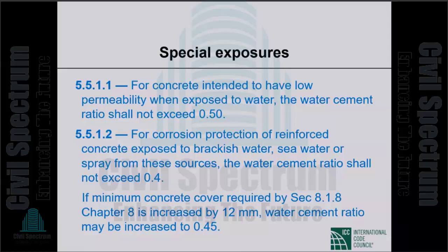Okay, so for corrosion protection, it's a much tighter limitation on water cement ratio. If minimum concrete cover required by section such and such is increased by half an inch, so the required cover is 3/4 of an inch, you provide an inch and a quarter, water cement ratio may be increased from 0.4 to 0.45. Okay, so that can be relaxed. The 0.4 can be relaxed to 0.45 if you are prepared to use a thick cover.